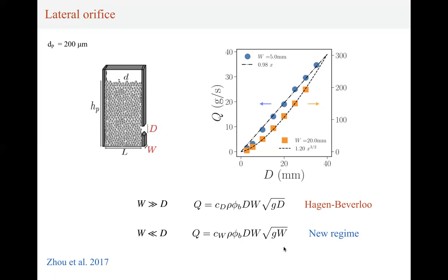We think that there is a dilatation at the orifice, which is linked to the volume fraction, so the volume fraction contains the effect of the size of the particle. But we cannot model it using Basilisk because Basilisk is incompressible. So if we want to model that, we have to go to a compressible model. But I think it is on the mu(I) and phi(I) rheology. It's still on research. Okay, thank you. Very good.